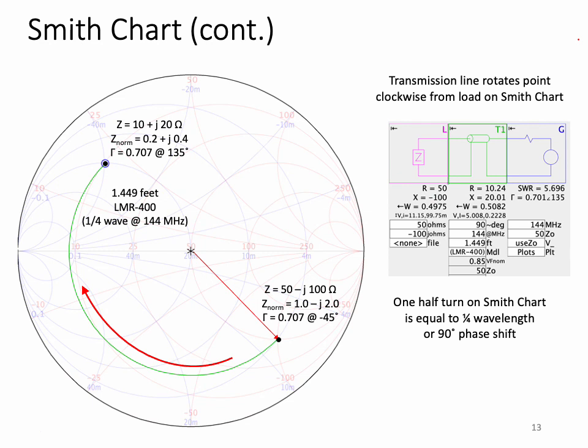So the impedance rotates from the original point, which is 50 minus j100. It'll rotate 180 degrees around the Smith chart to a point diametrically opposite. And at that point, the normalized impedance is 0.2 plus j0.4, which corresponds to an impedance non-normalized, in other words, multiplying back out by the characteristic impedance of 50 ohms, to be 10 plus j20 ohms.